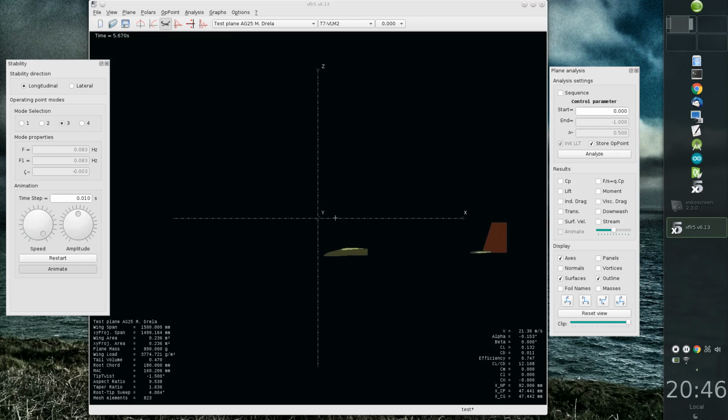So if this were horizontal steady state, the plane would have this motion around steady state, and this is called the Phugoid mode. This view is in the plane referential. When you see it flying, it will be a sort of nose dive and a sort of Russian mountain type of flight, going up and down.